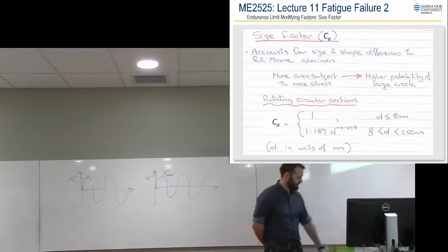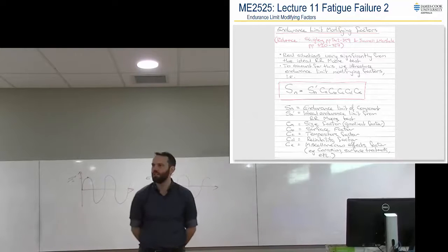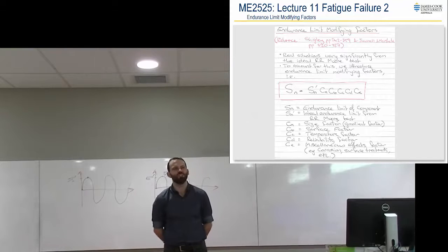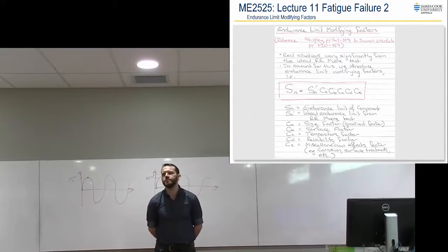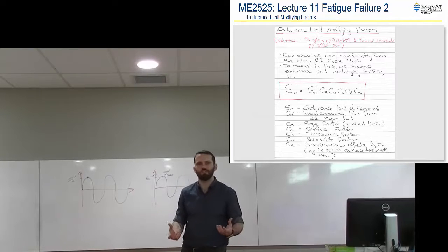Now this is our rational thought process here. Think about what CA, CB, CC, etc. do. Should they be making SN dash more or less? Less? Everyone think about that for a second. More or less? More. More? Is there a different option? So, what do we need this to do? This is effectively our yield stress. If I increase the yield stress, is that good or bad? Good. Would we expect damage to increase the yield stress or decrease the yield stress?